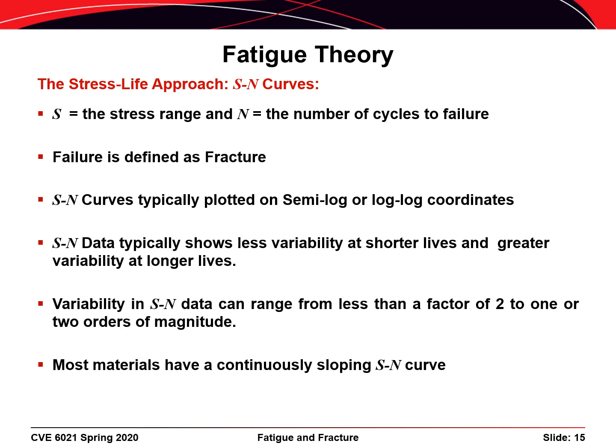Depending on the loads that are required and the stiffness of the components, the rate of loading can be anywhere from 2 seconds per cycle up to 5 cycles per second. Some components can sustain millions of cycles before failure, so constructing an SN curve can take a lot of time. If you were testing at 2 cycles per second, for example, it would take approximately 6 days to reach 1,000,000 cycles. And that's assuming that the system can operate 24 hours a day without having some sort of interruption.